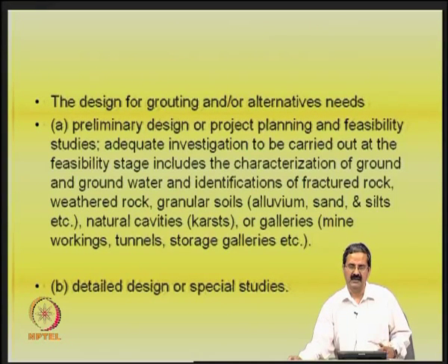You must be able to identify the type of grouting, the type of installation, the type of quality control you are going to have, and all that. One may even try a preliminary study on how it can be helpful in a small area and then extend it to a larger area, because you need to have experience with the technique. Once you have the experience, then it is quite easy to adopt.